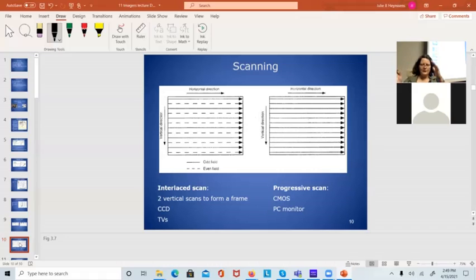Okay, now this is probably the camera turned on its side. Now what happens here is this row gets reset first and it gets read first. So this is an earlier image. This part of the image happens earlier in time than this part of the image. It may be milliseconds if you have a fast camera.